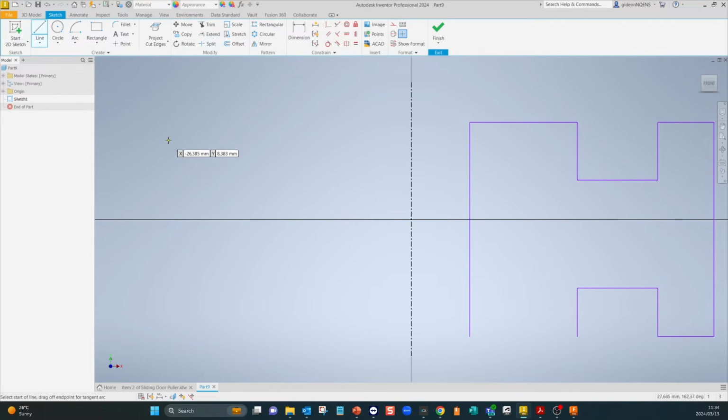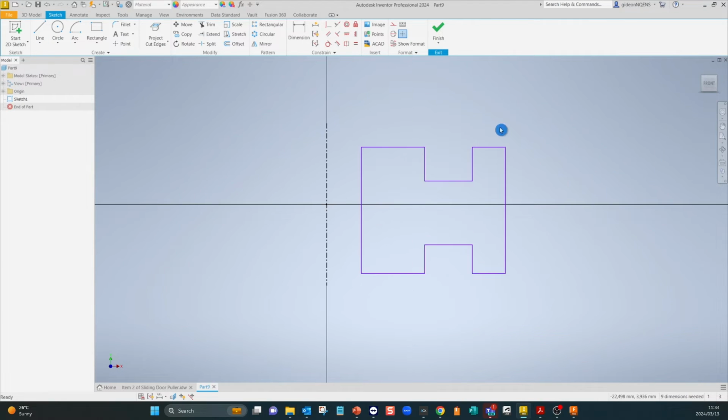One important thing to remember, when you use the revolve function, you need to have a closed profile. You will not be able to revolve if you don't have a closed profile. Just using a line and closing the command. So that is more or less what I've drawn.